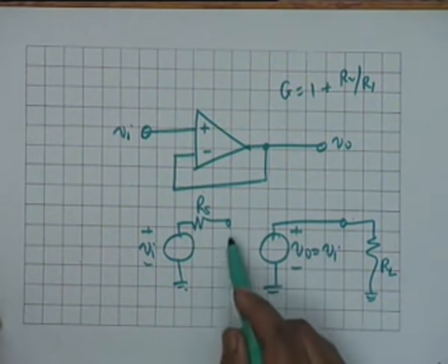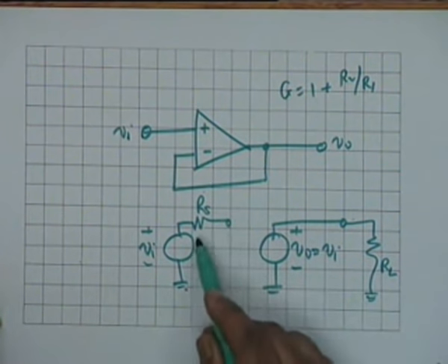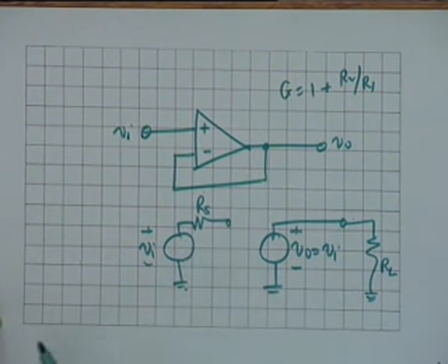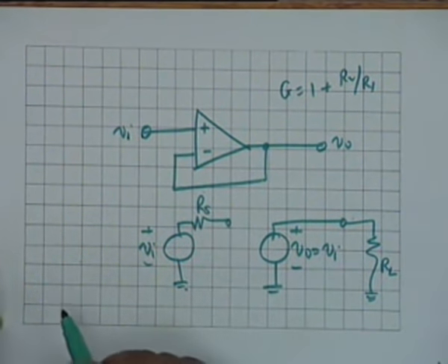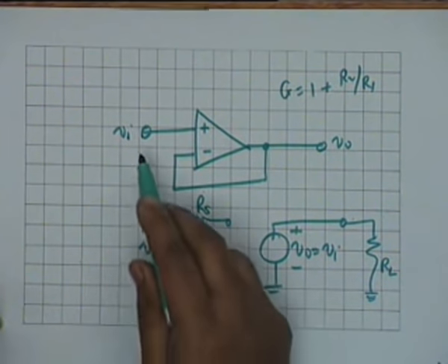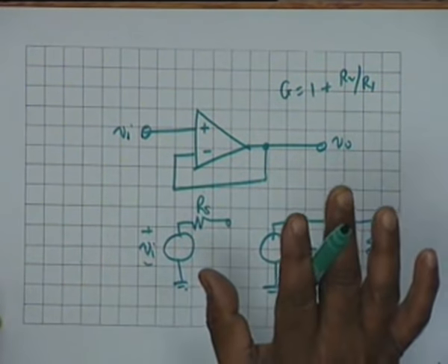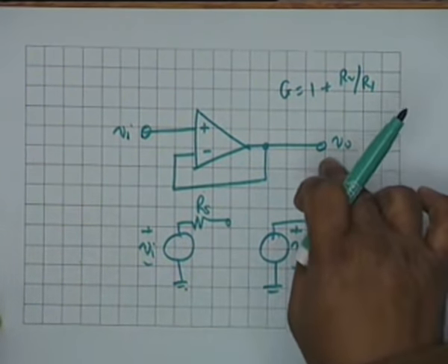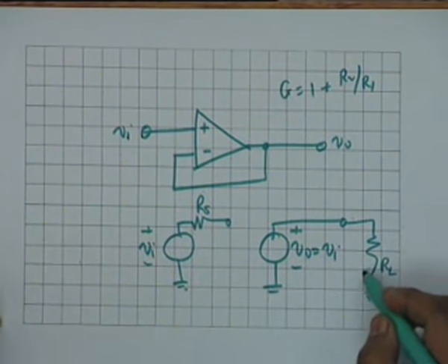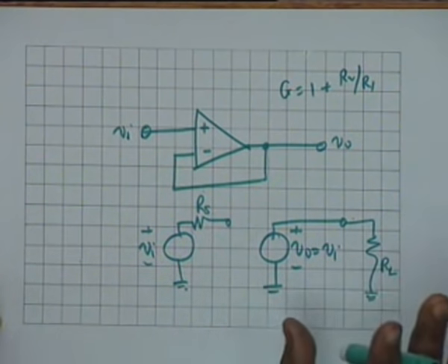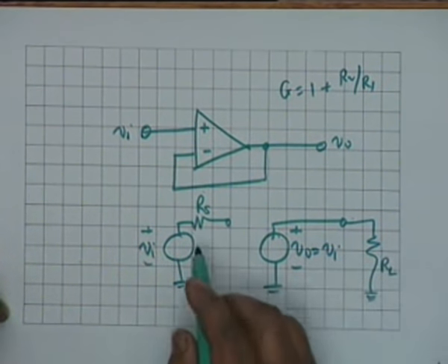In other words, the load current would depend on Rs, which is not the case here, because whatever the source impedance is, Vi is transferred directly to the output, and therefore the load voltage shall remain Vi irrespective of what Rs is.